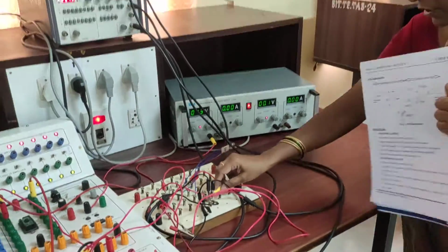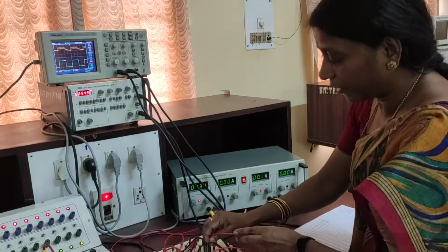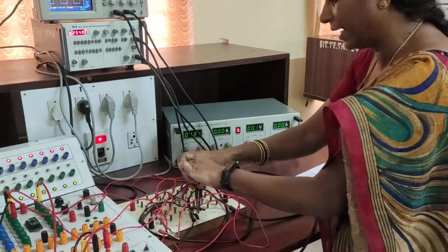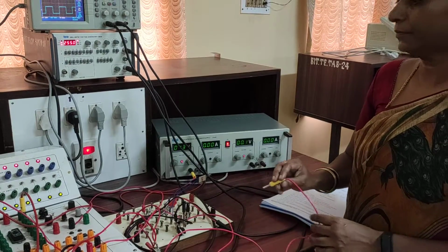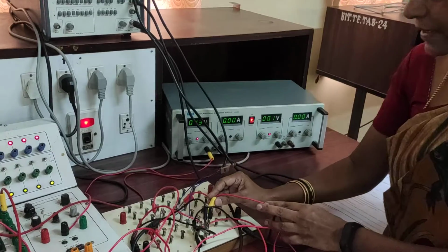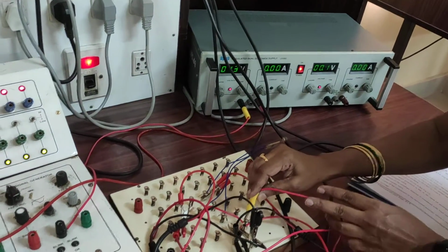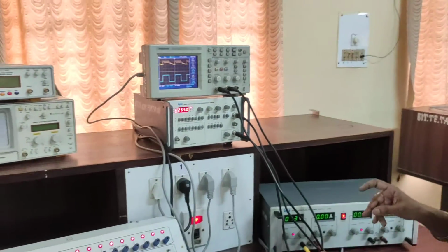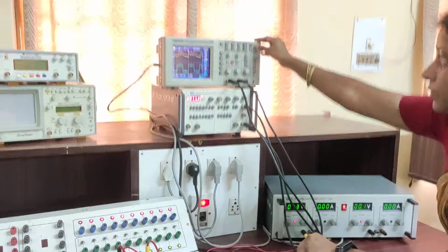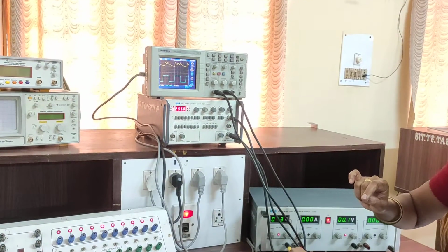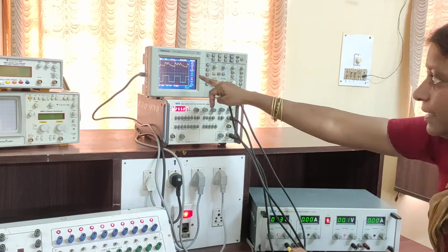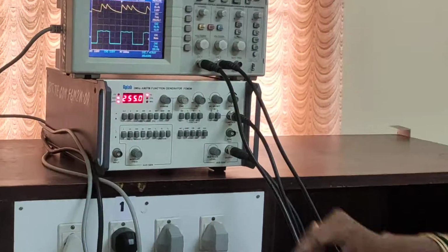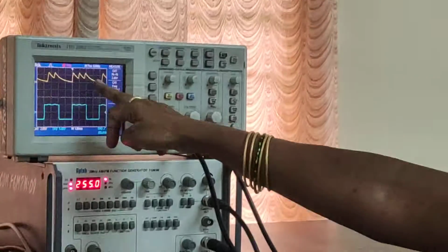So I am showing you the envelope detector output. Okay, so this is your envelope detector output, which will have only the charging and the discharging. Output of the diode is connected to the envelope detector circuit. Okay, I am connecting here the envelope detector. You can see the waveform. So this is the charging and discharging waveform. So whenever signal is there, you are getting a charging and discharging. Okay, and when signal is not there, you are getting a 0 signal.